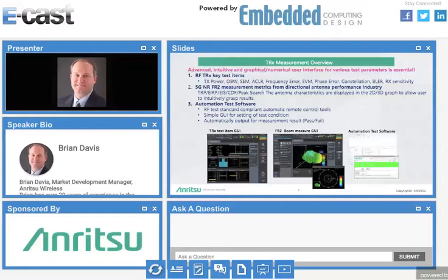Now, when we get to 5G, the test equipment industries had to evolve for the millimeter wave side, right? Because you can't bypass antennas and do coupled testing like you could for sub-6 gigahertz. The antenna's integrated with the baseband, with the RF front end and all that.